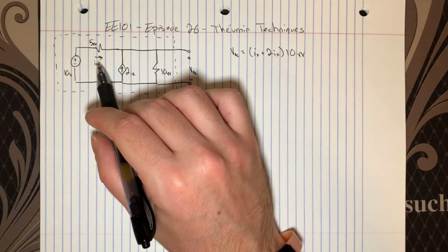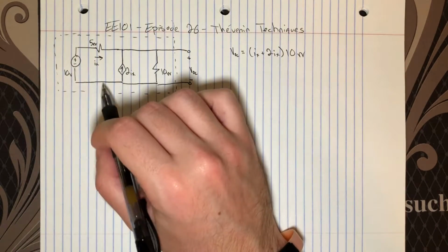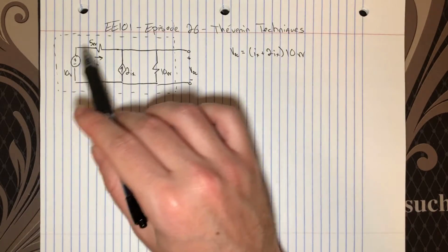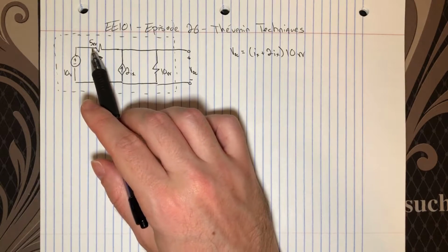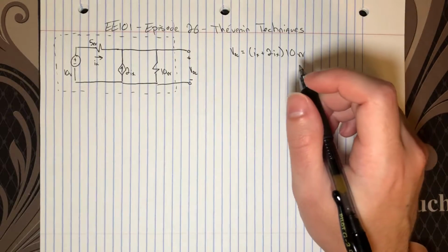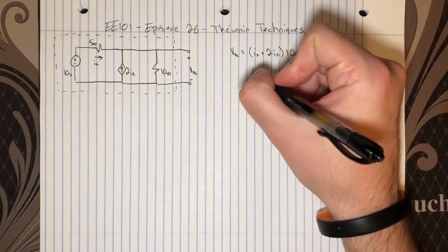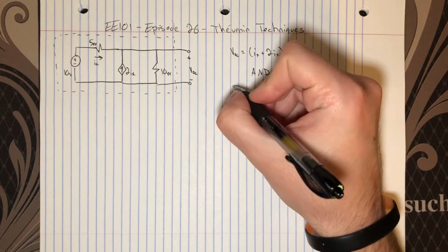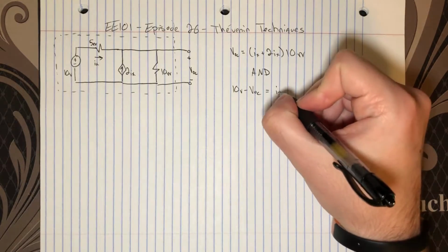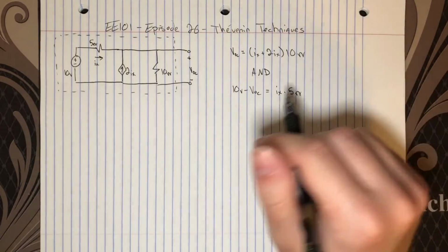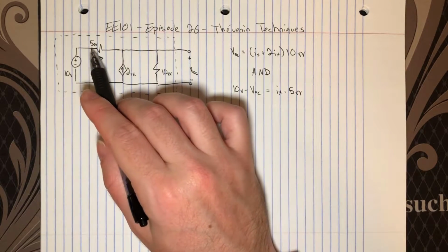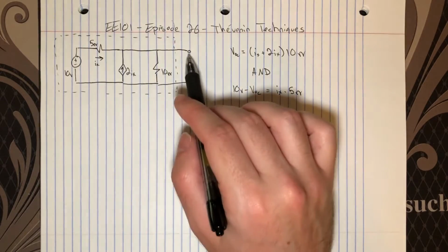To look at IX, I'm going to try and do a voltage analysis, so a loop analysis. So we have VOC, we have the source voltage. The missing link in that loop is the voltage across the 5 ohm resistor. So Kirchhoff's voltage law tells us that 10 volts minus VOC equals IX times 5 ohms. What that means is that we step up 10 volts, and that total 10 volts has to be dropped, so some will drop across 5 ohms, but all that's left is VOC.